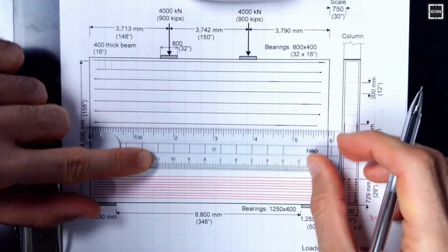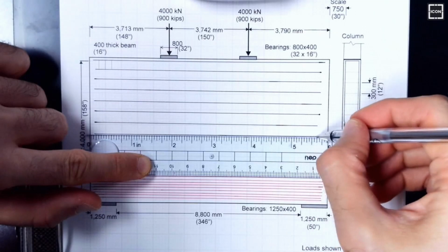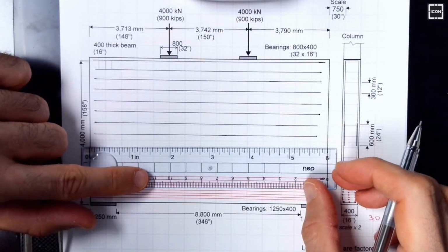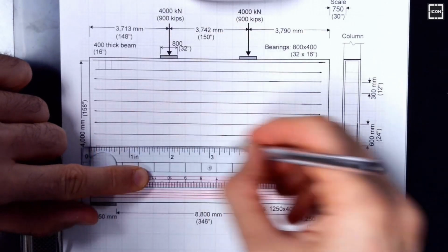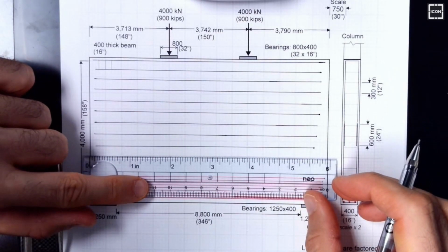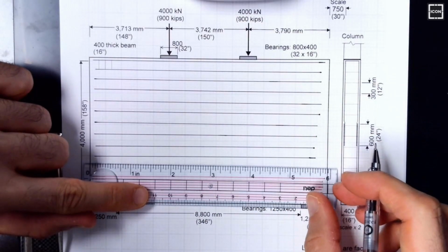For older systems, we don't see it. We don't have crack control reinforcement, so penalties would apply. You would go with 0.45 multiplier. We use 0.65 for this. If you didn't have crack control reinforcement, many things would have failed for this model.